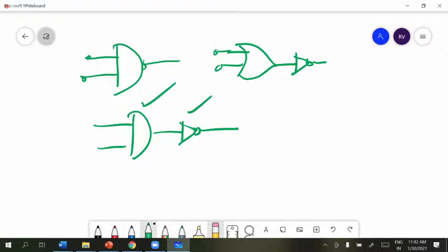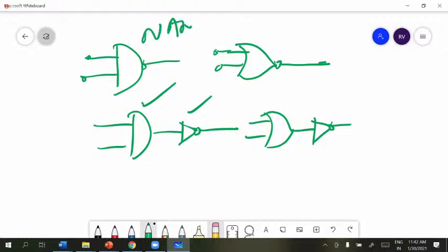Using the OR gate, using discrete components, you know. So using discrete components, this NOT gate also you know. So you can easily do it. This is a NOR gate, right? So this is a NAND. This is a NOT. These are universal gates. Using only NAND gates, you can design any big logic circuit. Using only NOR gates, you can design any big logic circuit.